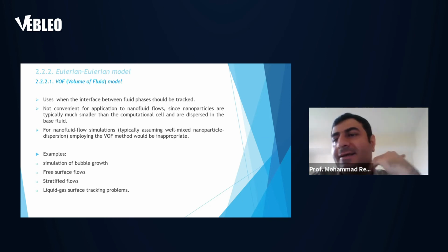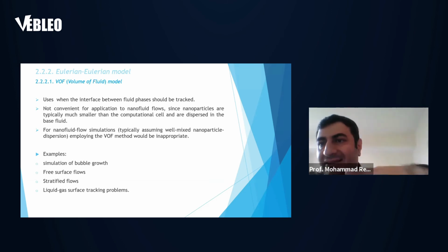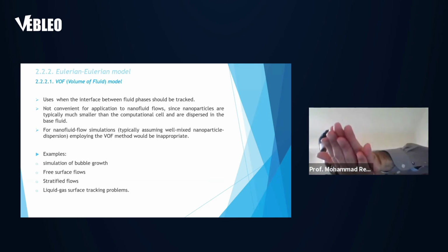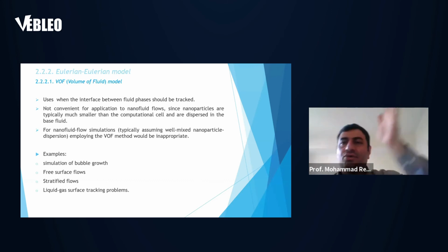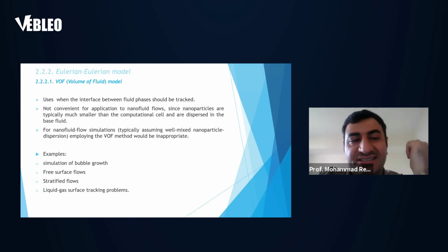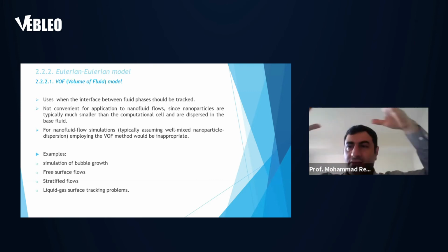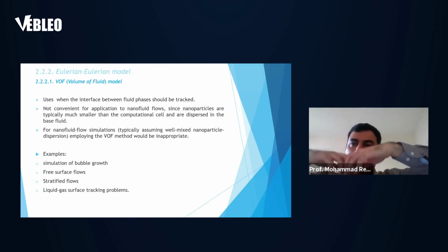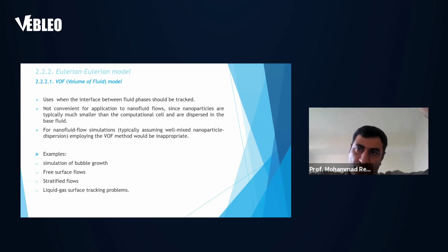For example, there's water in a dam, and the water has an interface with air, okay? If you want to do that modeling, of course you use VOF because it's a free surface, or you have a bubble inside the fluid that grows and pops. Of course you use this model. But this model should not be used for nanofluid modeling.